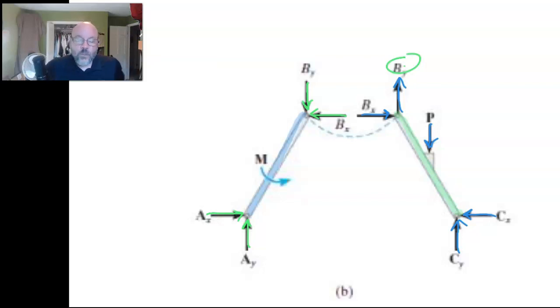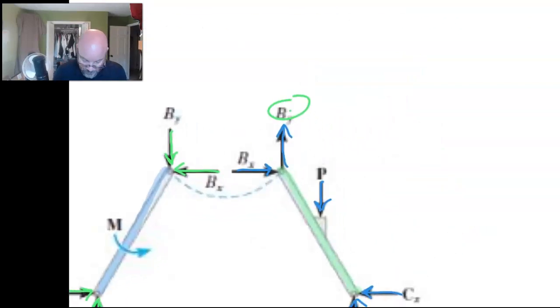But this is what we are going to get a handle on. Now, once we have exploded our image, our object, and we're looking at the different forces acting on it, at that point we use all of our regular equilibrium tools. So on each of these components, I'm going to look at Fx, Fy, and I'm going to pick a moment.